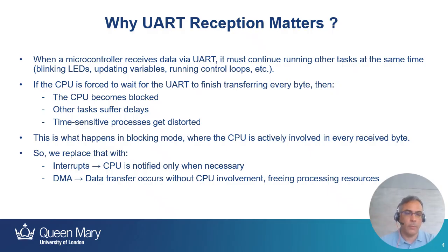To overcome this, we replace that with interrupts, so the CPU is notified only when necessary, or we move to the DMA. With DMA, the data is transferred without the CPU involvement, freeing processing resources.